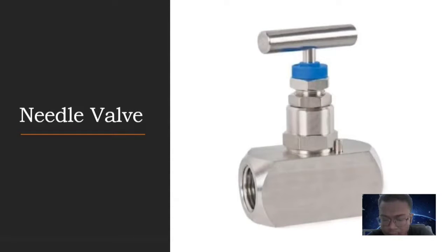The needle valve. It is a kind of screw-down stop valve. It's restricted to small sizes which have the body ends in line or at right angles with each other, or maybe oblique type. Here, the stem is in the form of a needle point. By rotating the hand wheel, the tapered needle advances, and the area of the valve tip decreases. Hence, the outflow is gradually reduced. These valves are used in hydraulic systems in lines of delicate pressure gauge.